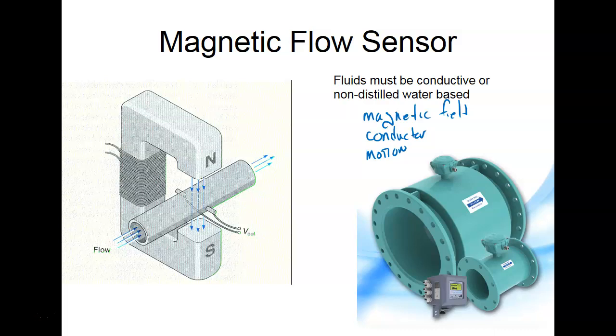So what we do prior to the sensors is we have a magnetic field. The fluid passes through a magnetic field, and then that fluid passes through these coils right here that are mounted on each side. And the rate of the motion would give us what? Flow, right? This would work with most liquids. Probably wouldn't work with something like distilled water, but most liquids have particles in them that would react to the magnetic field. So this would work on most liquids. Probably wouldn't work on gases.